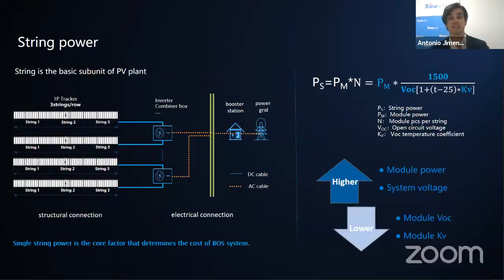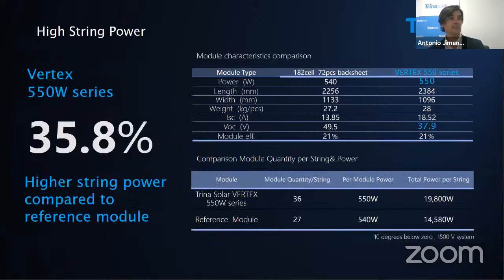What we are doing is this: instead of 2 strings of 9 amperes, we have 1 string of 18 amperes. It's the same, so the losses are similar. There are no more losses of current. What we have is more power, which reduces the BOS, and which determines the cost of the plants.